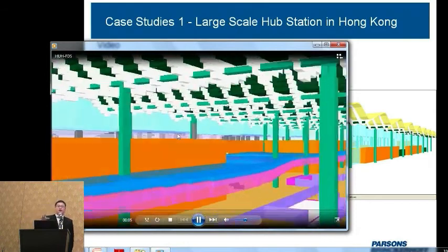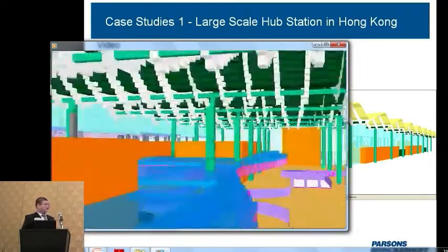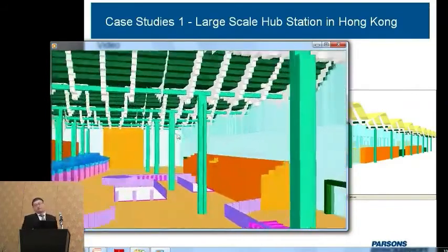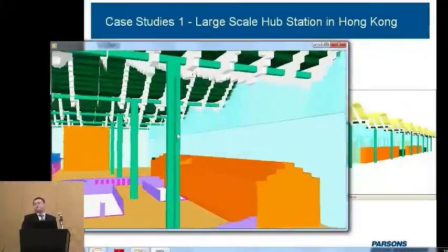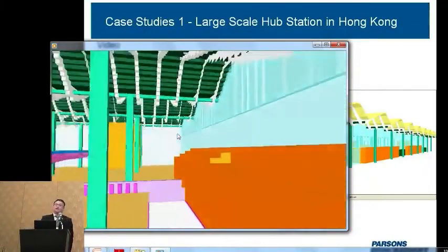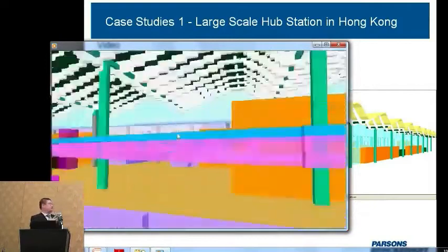We have a refined zone around the fire, but normally the grid size for other features is 0.4. But even if you refine it to 0.2, which means 8 times the mesh count, it still won't catch the detail.